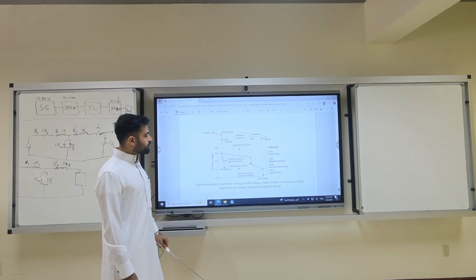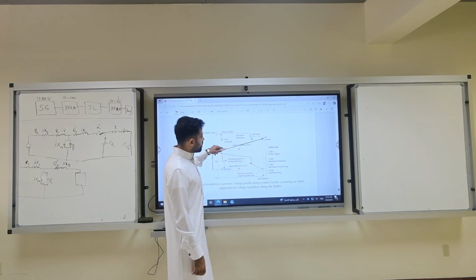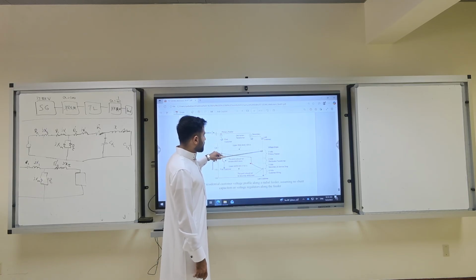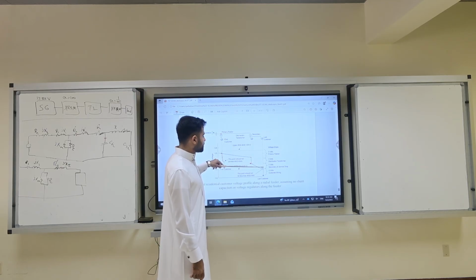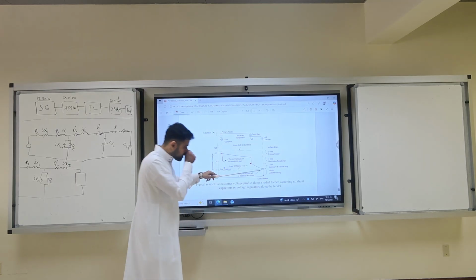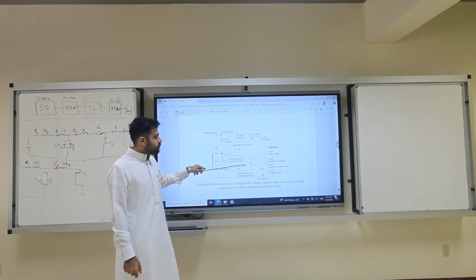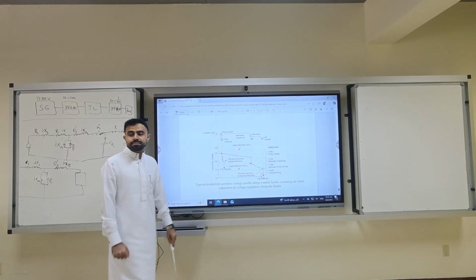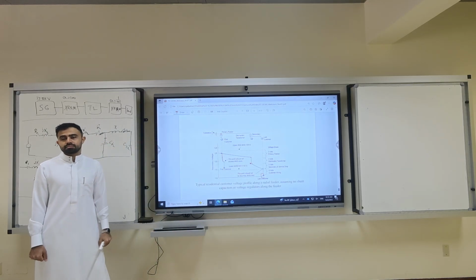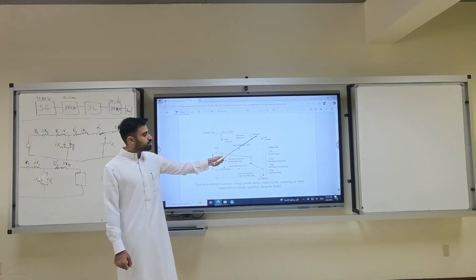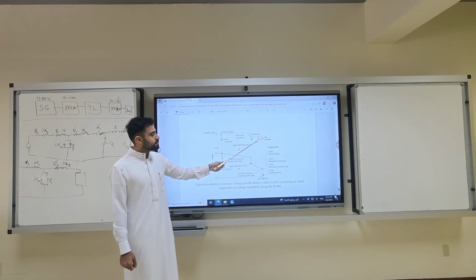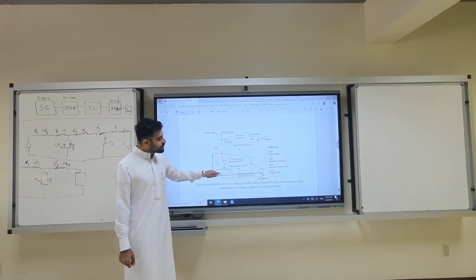The problem comes at the last customer, where the last customer lost the primary feeder, distribution transformer, secondary and service drop, and internal wiring, 4 volts lost. So it's below the 114. So the last customer is at danger. Because this is a bad design. That's why here we need to have a capacitor bank. If we have a capacitor bank, we'll increase the voltage.